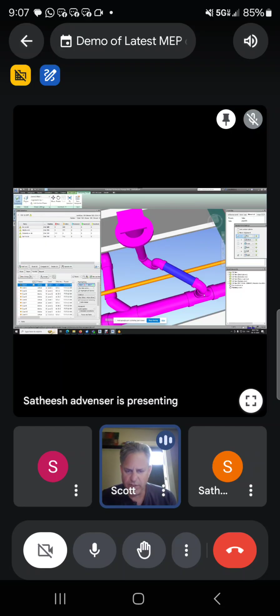Because when we assemble this in a shop, being an 1/8 inch off here and another 1/8 inch off over here, all of a sudden we're a quarter off. Now we're a 1/2 inch off. All that stuff kind of comes into play.